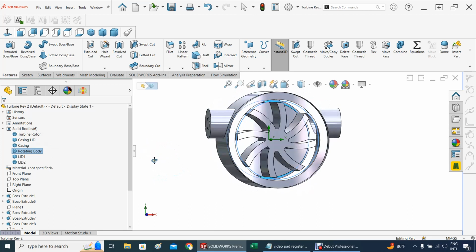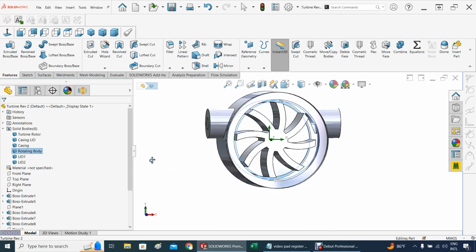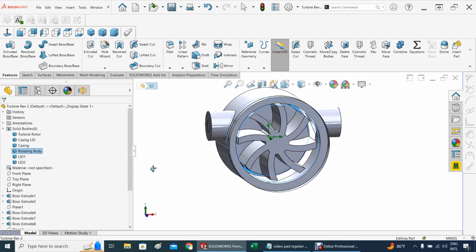like you create a body to enclose what is going to be rotating, and that's very important. Sometimes if you are new to SolidWorks, it's kind of hard to understand this part of flow simulation, because basically within that rotating body you put whatever is going to be rotating, so at a later time you will see it moving and it starts to make sense.